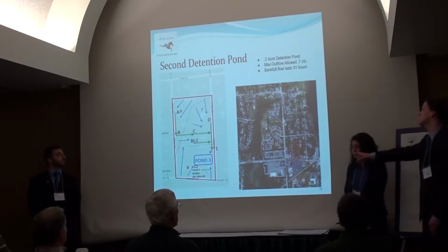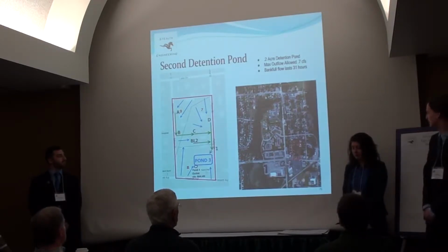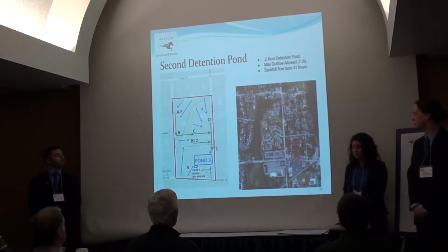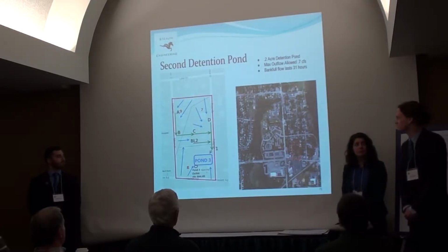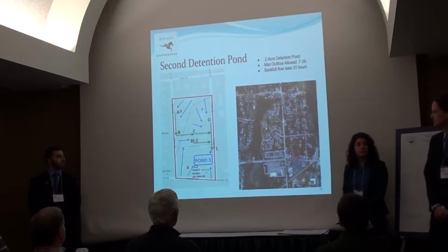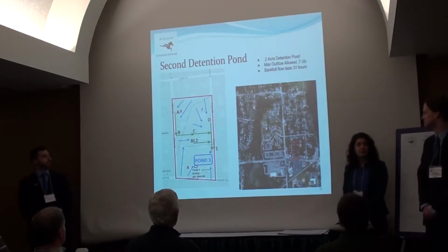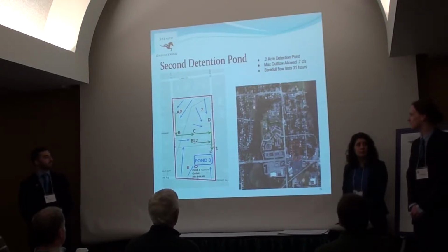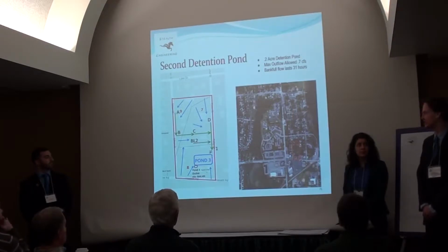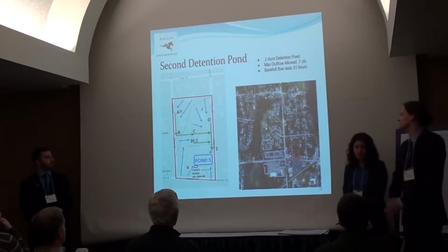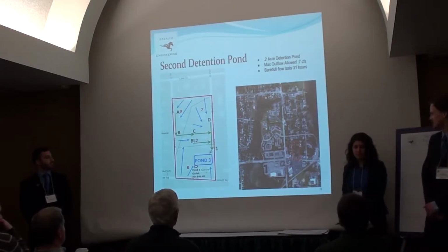For the main area of concern, this 5-acre piece of land where most flooding has occurred, we had designed swales to go in through backyards, which would need easement. If not, we would be able to place piping to help these people take care of their flooding issues. The runoff paths show that most of the water should be captured by these swales and taken to pond 3.